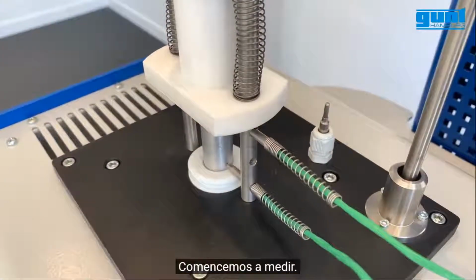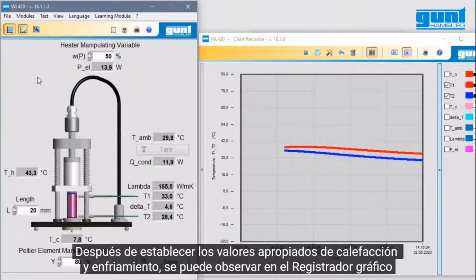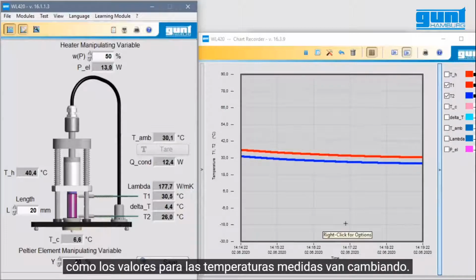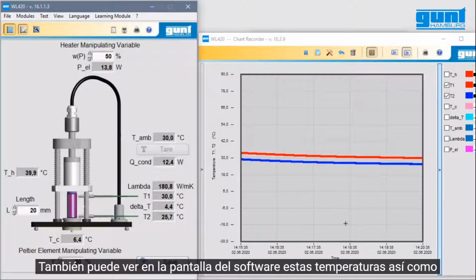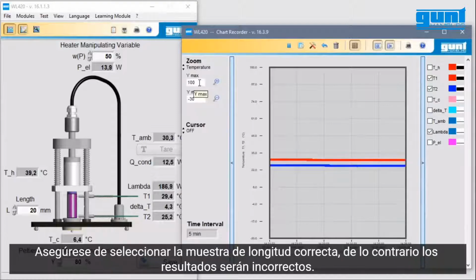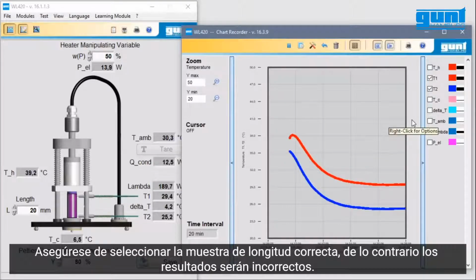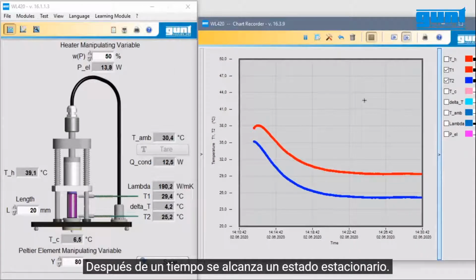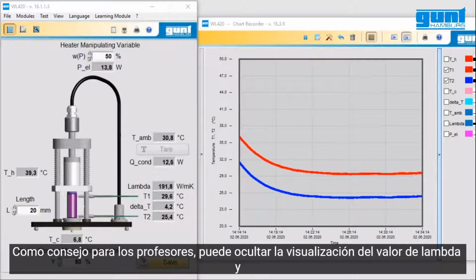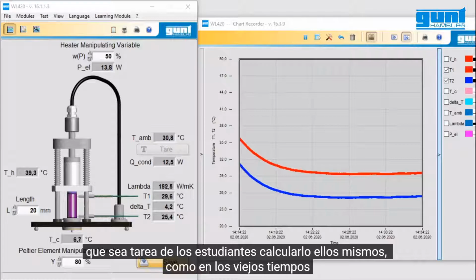Let's start measuring. After setting the appropriate values for heating and cooling, you can observe on the chart recorder how the values for the measured temperatures change. You can also see in the system overview these temperatures as numerical values together with the calculated heat conductivity lambda. Make sure you select the correct specimen length, otherwise the results will be incorrect. After a while, a steady state is reached. As a tip for teachers, you can deselect the display of the value for lambda to task the students with calculating it themselves, just like in the old days.